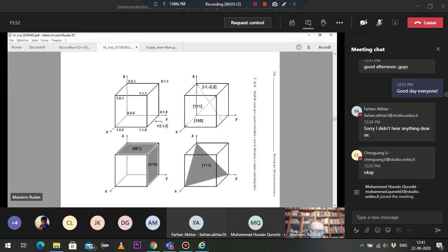When you consider crystallography, you must avoid non-integer numbers. So you simply multiply these numbers by 2 in order to eliminate the denominator. So minus 1/2 after multiplication by 2 becomes minus 1.